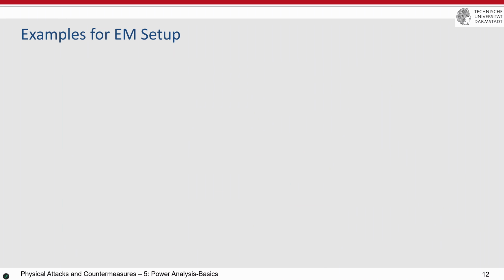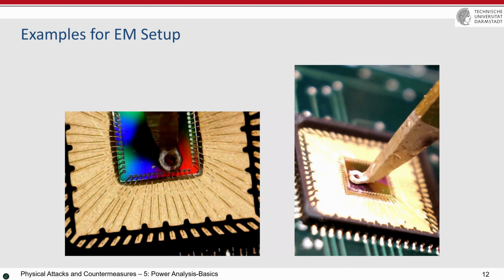I will talk about the capacitors a bit later, but these are not the only type of EM probes. Some other EM probes are super tiny and small. They are localized EM probes. This photo or these photos are super enlarged. The size of this EM probe is 150 micrometer in diameter. That means you cannot manually position it. If you position it manually with your hand, you will definitely touch these bonding wires, and they will destroy it, and then the chip will not work anymore.